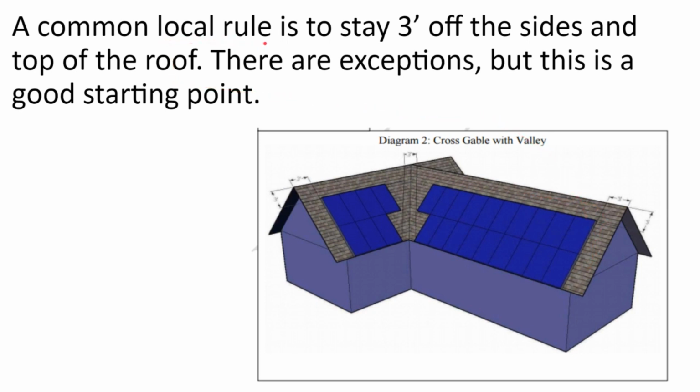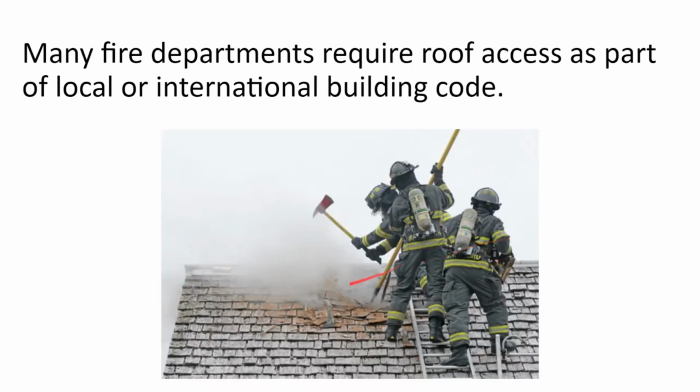The main concern is that a building need an exhaust plan to ventilate smoke from attic spaces and lofted ceilings in the event of a fire. So if a sleek edge to edge modern look of a residential solar home is desired, know that it is possible to obtain exemptions from these 3-foot offset rules on slanted roofs, even when mandated locally, if other kinds of ventilation systems are planned in those spaces.